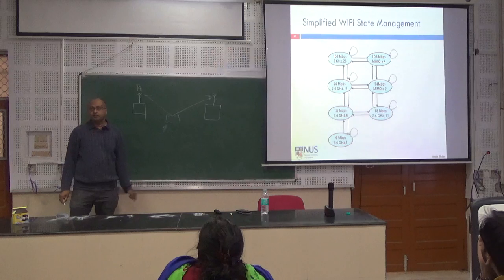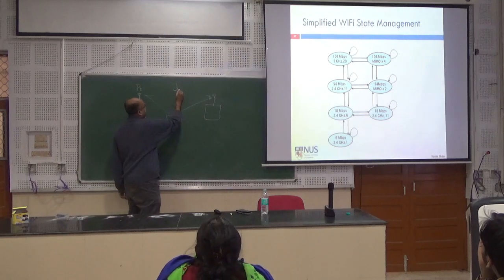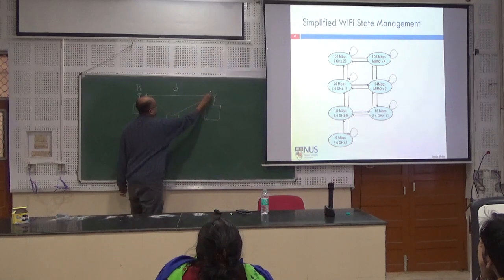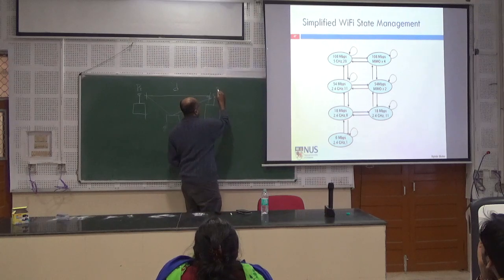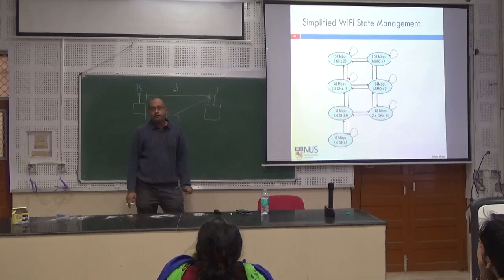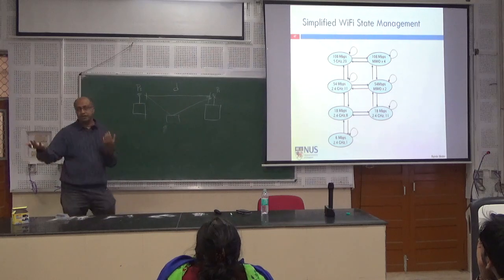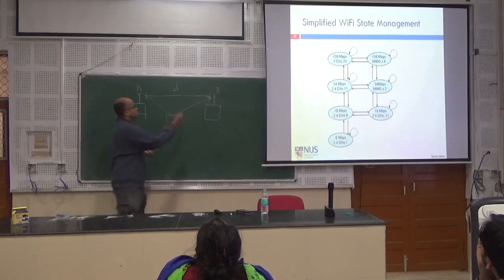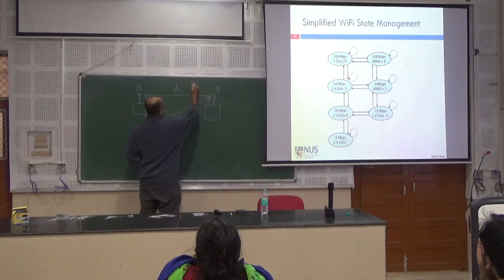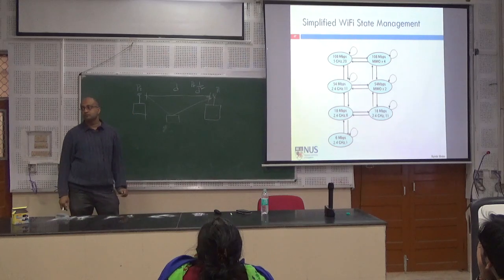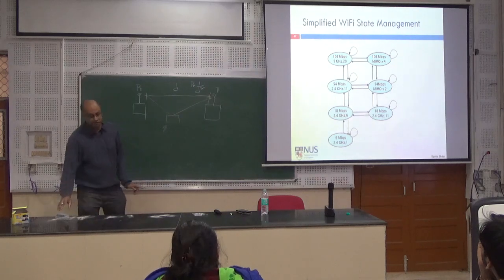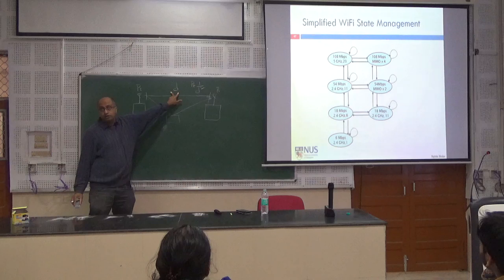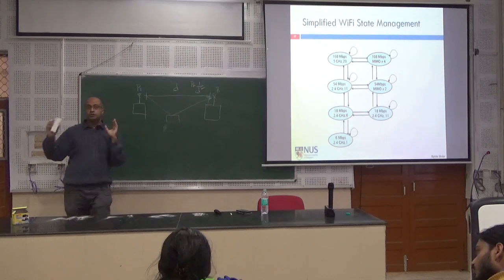If you know the transmit power, and if you know the distance between these two, then you can figure out the receive power here. If there is line of sight, you expect something of the order of PT times 1 over d squared, where d is the distance. If it is non-line of sight, this is the main component, or the strongest component. The reflected waves usually are much smaller.